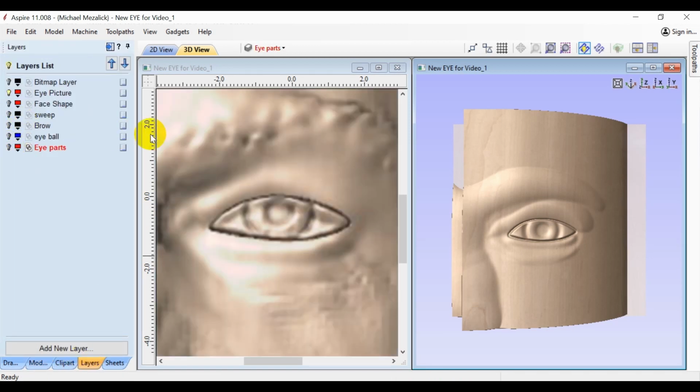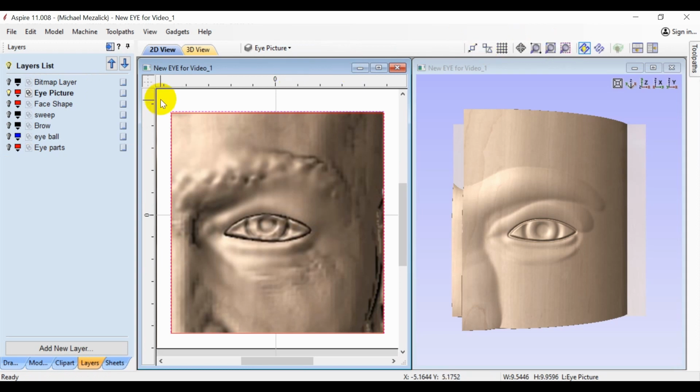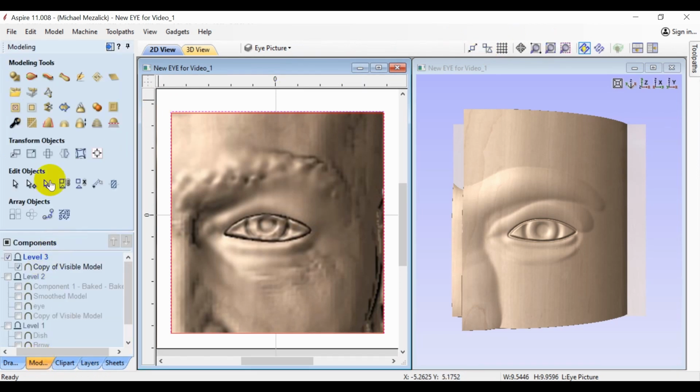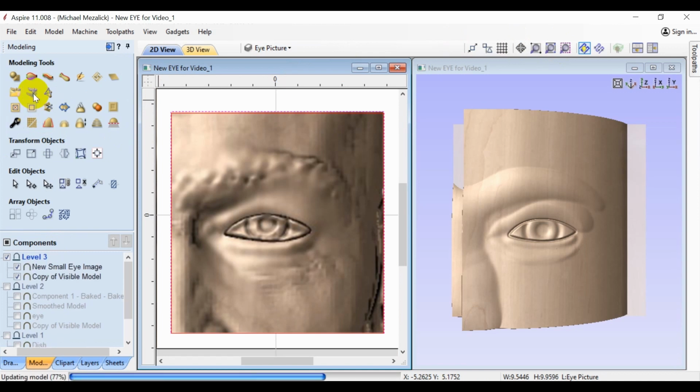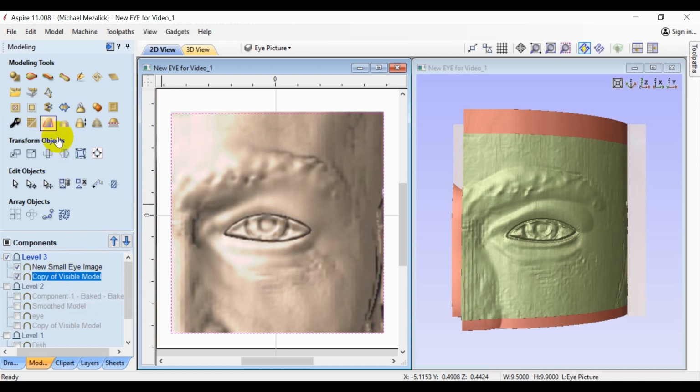There's the original picture of the eye and our component. I think we're getting pretty close. I could create a skin, a component from the picture, by clicking on our Create Component from Bitmap option, and apply that to the top of our model, adding a bit of texture to the face. I'm going to do a bit of trimming of our base shape simply by drawing a vector around our picture and keeping everything inside of it, so it's nice and tidy.